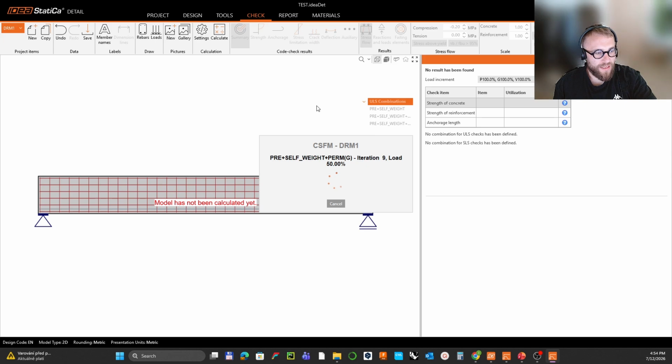And also the bond is included, where there is a nonlinear relation between the force and the slip, or stress and the slip, that looks quite rigid and with a big plastic elongation or permanent deformation of the slip.